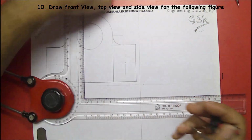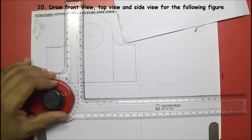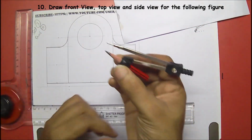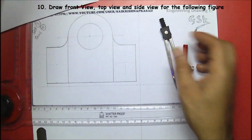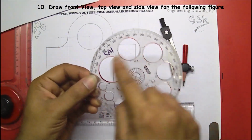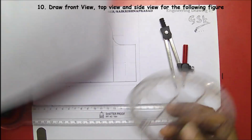So the diameter of the hole is 12, means I have to create a circle of 6 radius. Creating a small circle with this compass would be very difficult, so for this I'll be using this pro circle. It already has some circular holes in it. So I have to select the diameter 12, right? This is the diameter 12.